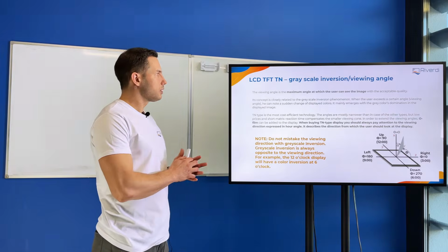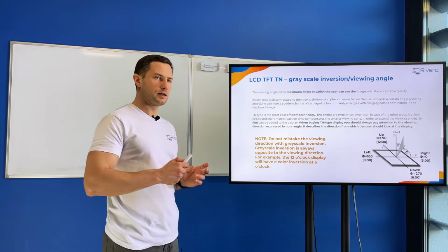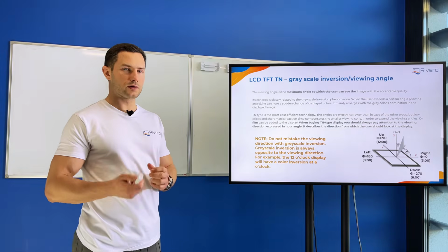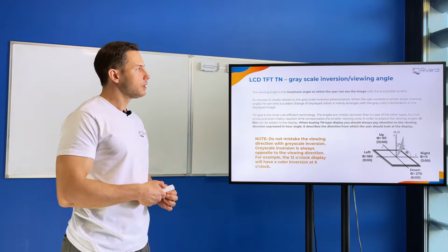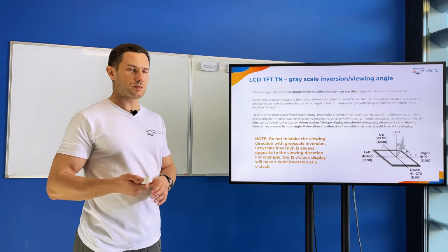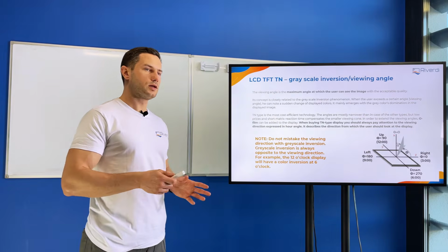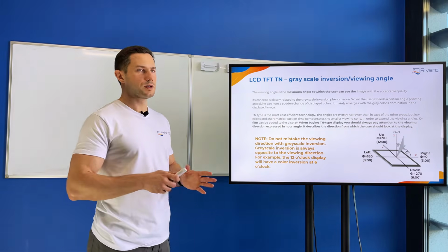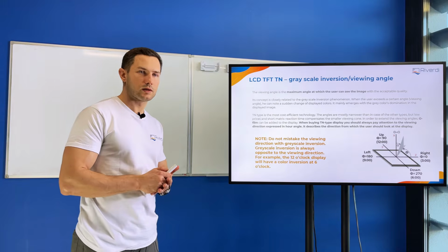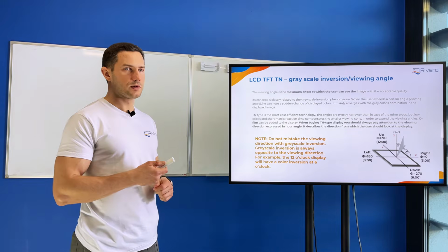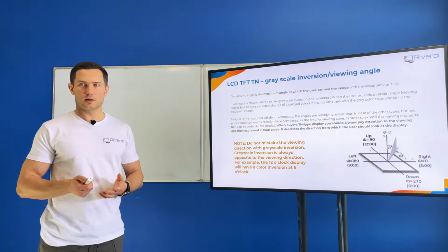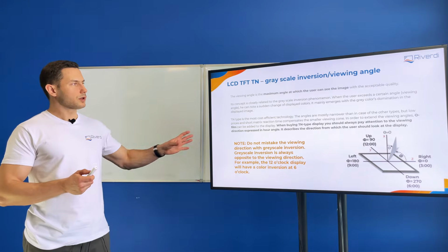Yes, so usually when we buy a TFT display, we need to check first what kind of technology we have. If it's an IPS display, like the Riverdi IPS display line, then we don't need to care about it, because all the viewing angles will be the same and all of them will be very high, like up to 80, 85, 89 degrees. So this phenomenon is not there.